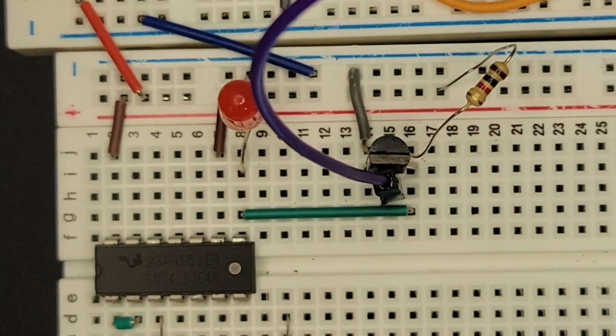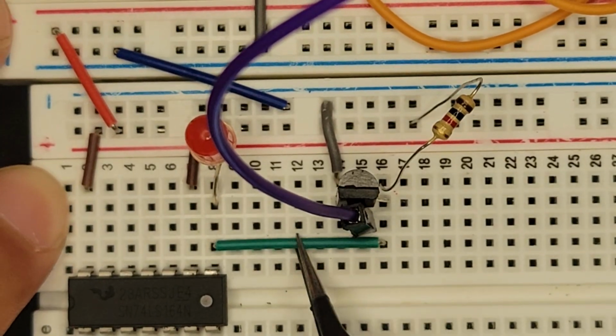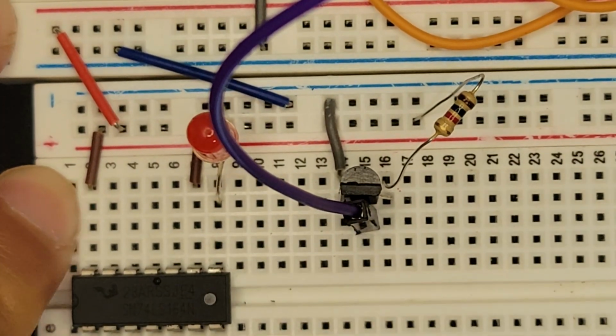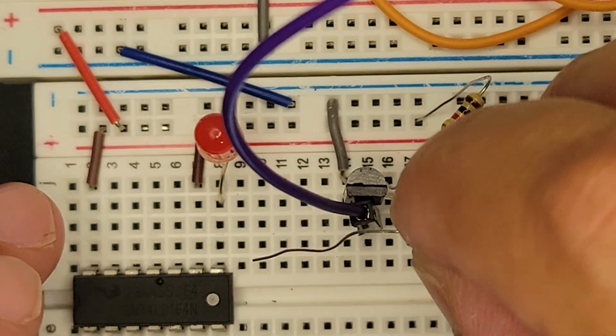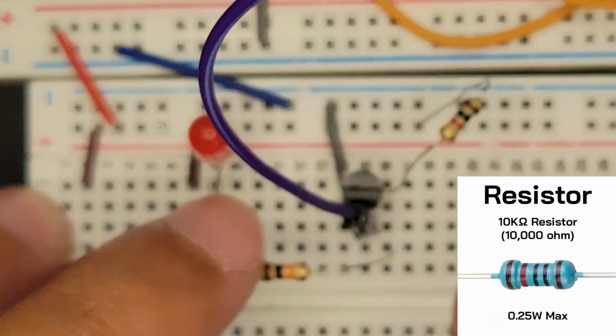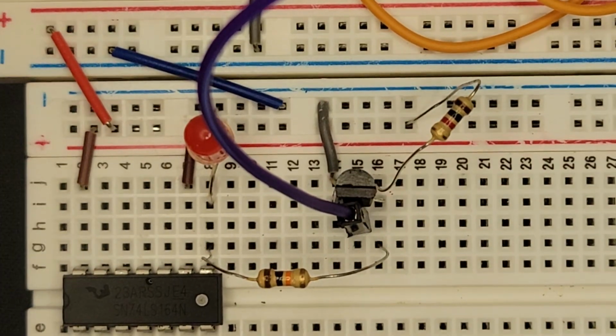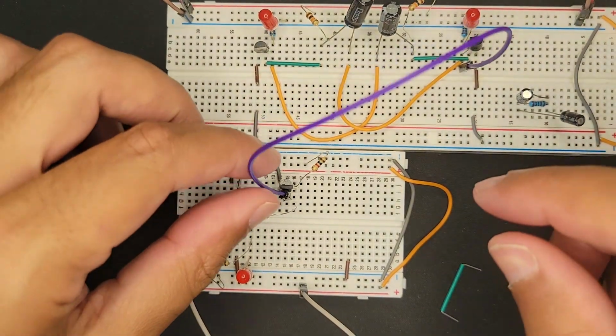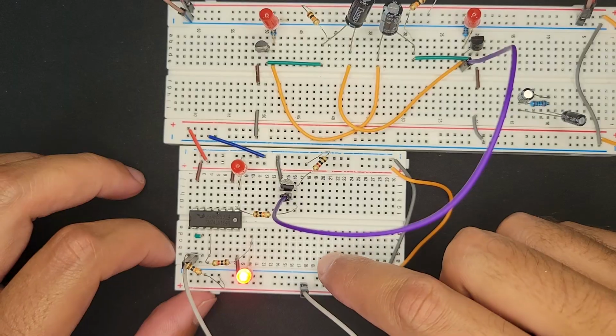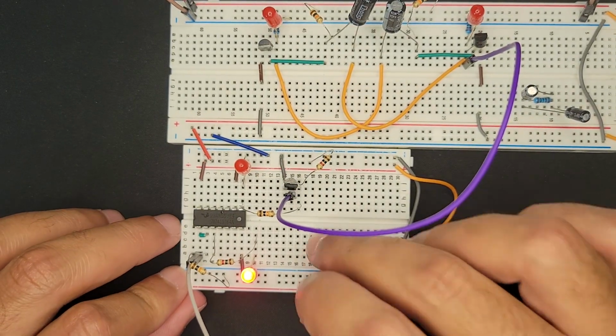Okay, so our green seems to work. Well, really, this should be a high resistance path. That's what I'm forgetting. So I'm going to use a 10K here to make a high resistance path, so it only wants to go this way when the base is not pressed. So I'm going to plug this in and see if that changes anything. All right, so we should have a 1 on the output, and there is a 1.